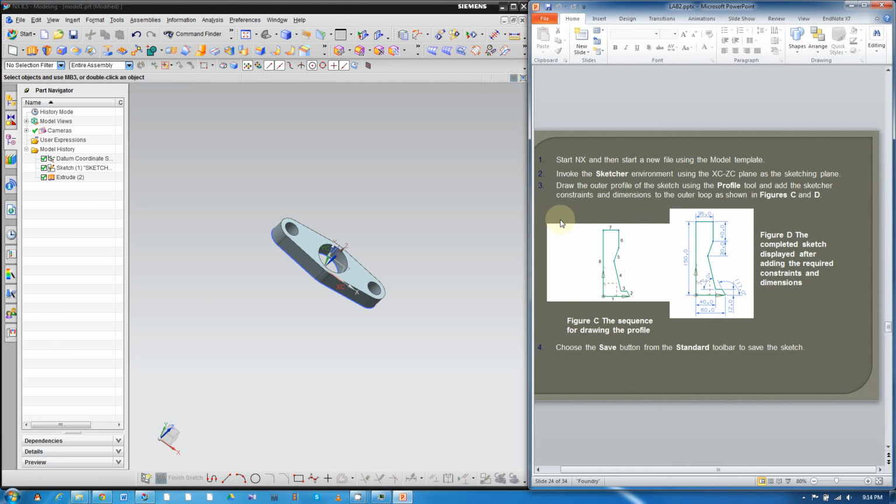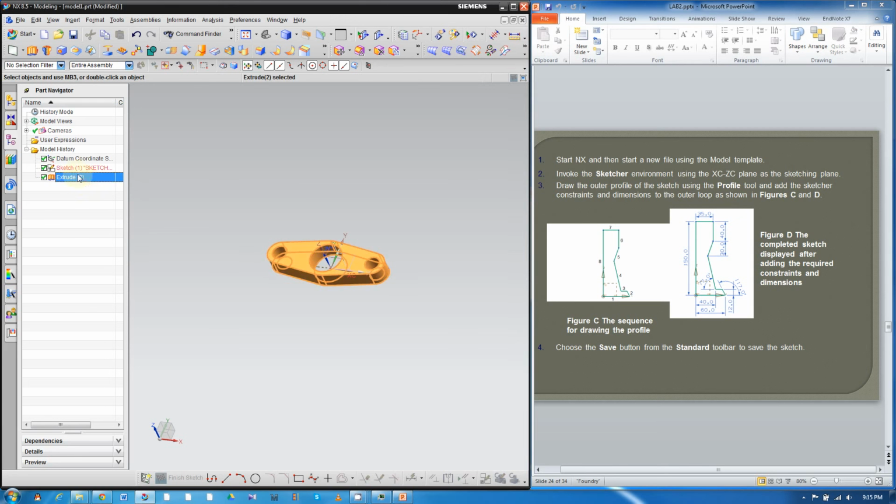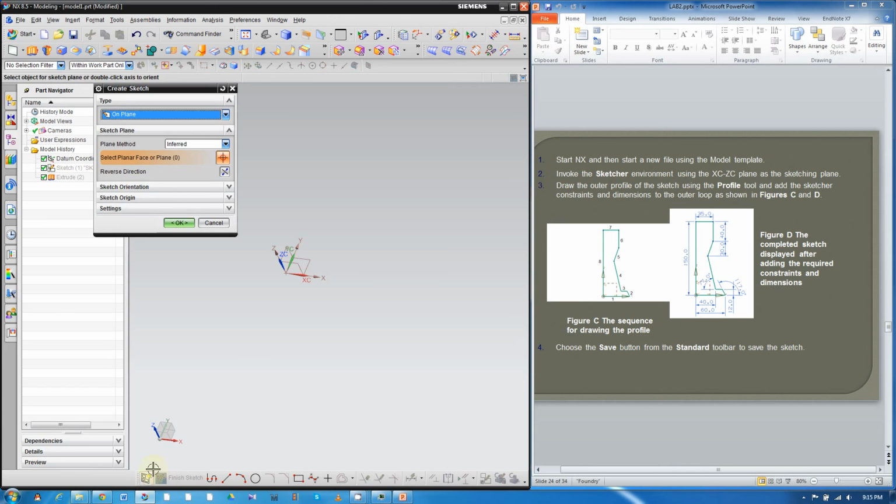Okay, I think I can do homework 1 also, because if you put in the dimension 1 by 1, then the shape will change, and sometimes people freak out. The shape goes too weird. Okay, and we'll see what happens. Now I'm gonna build a new sketch for homework 1, and we don't need homework 2 to interfere with our drawing. So we can right click and hide both these 2 features, so we have a clear working space. Then we can build a new sketch on XY again.